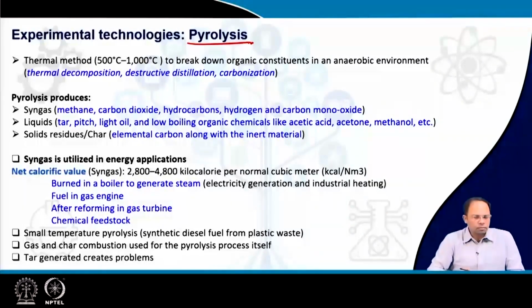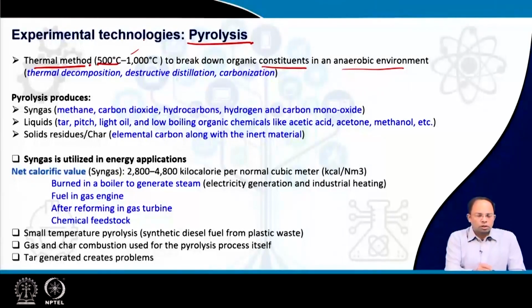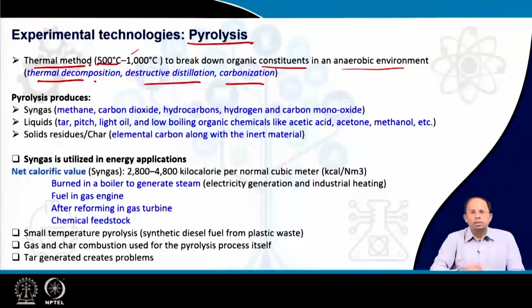So pyrolysis is also a thermal method or an incineration method you can call, where incineration happens at 500 to 1000 degrees centigrade to break down organic constituents in an anaerobic environment. So here the incineration, or the burning, happens in absence of air. But the temperature is much higher than the normal incineration process. So we also call it thermal decomposition. This is also known as thermal decomposition, destructive distillation, and carbonization.